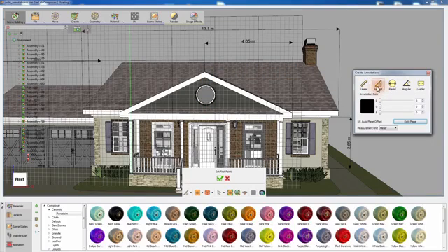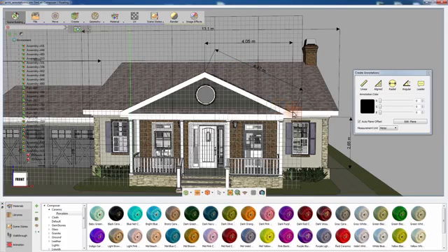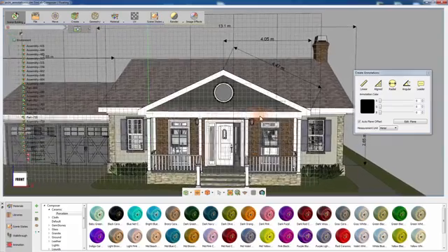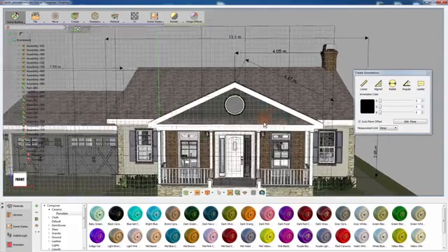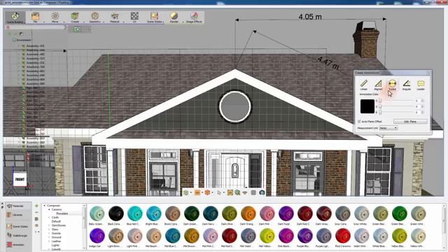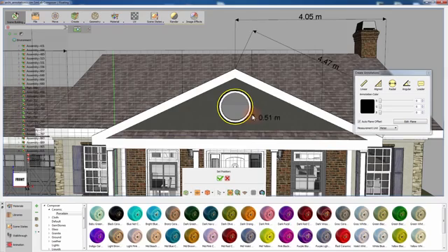Click on the Align Dimension tool and measure the distance between the same points you measured earlier. The Align Dimension tool will measure the distance between 2 points without projecting the values to the principal axis, which can be useful in measuring diagonal surfaces and edges. Select the Radial Dimension tool and click on the edge of the circular window to measure its radius. Click again to set the length of the annotation's indicator, and by moving the cursor, determine the length and orientation of the measurement's text.